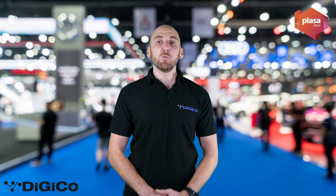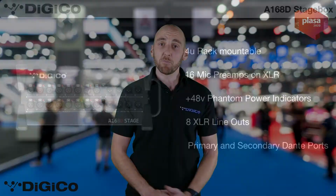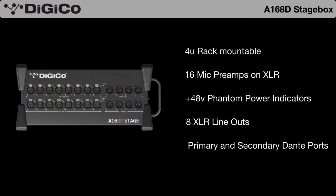First of all, we have the A168D. The A168D is a 4U rack mountable stage box that has 16 mic line inputs and 8 outputs. The plus 48 volts phantom power, gain and pad options are all controlled by the console over the Dante network. Included next to each input is a phantom power indicator.